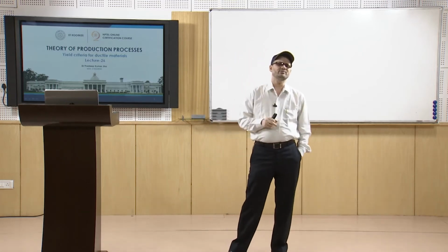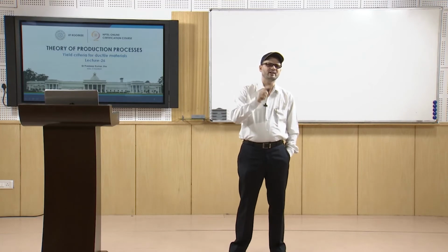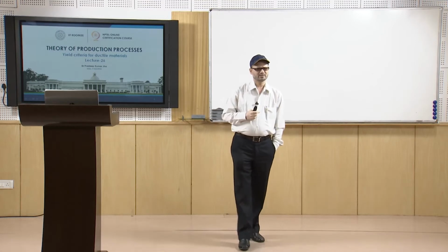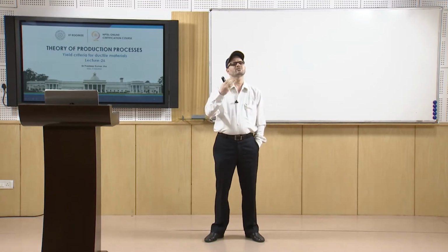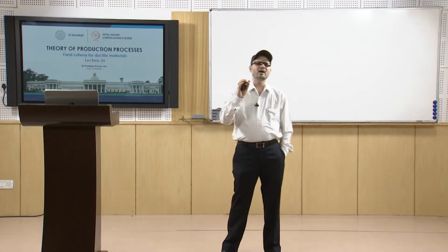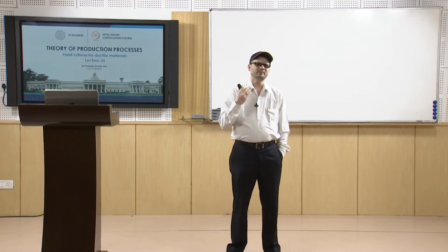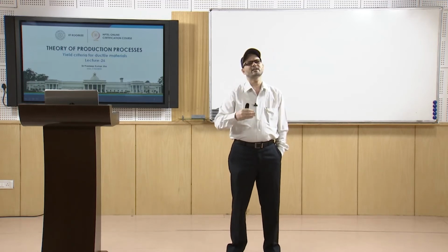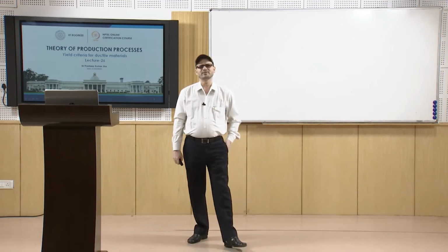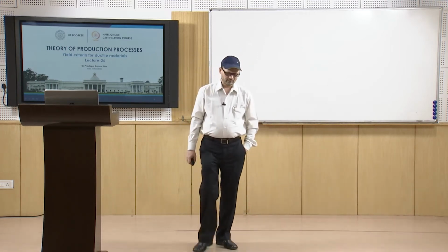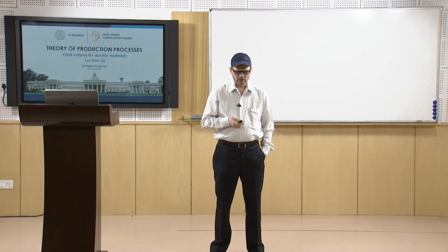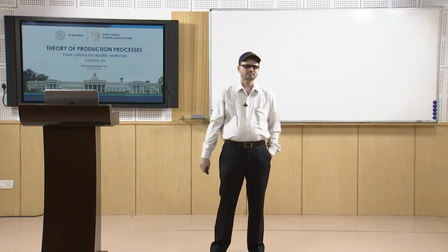Then the second stress deviator must be the one that is instrumental in telling us what the condition should be for yielding to take place. So, based on that, we are going to see different cases, the conditions under which yielding will take place. There have been certain methods, certain rules proposed, and one of them is by von Mises.